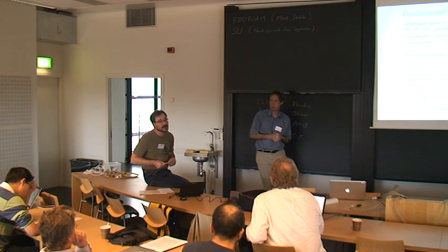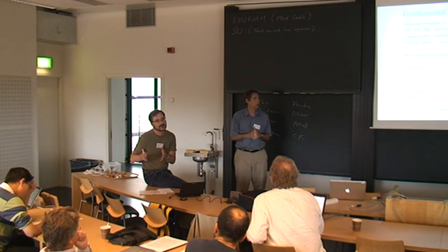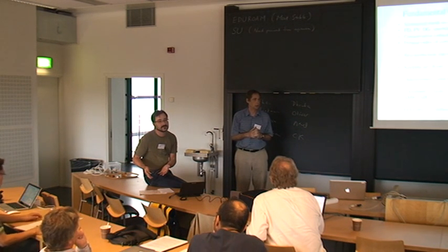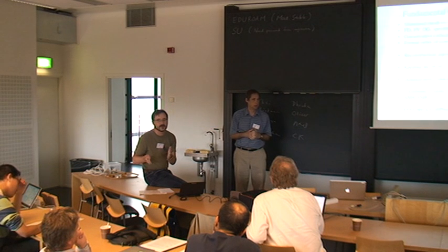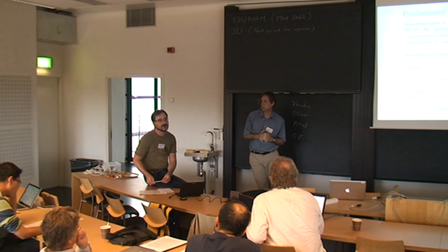I was actually more aiming at artificial viscosity versus some truncation, like in a Godunov scheme where your averaging will lead to some sort of dissipation, and how well that is understood and controlled, because there are no free parameters in a Godunov scheme.